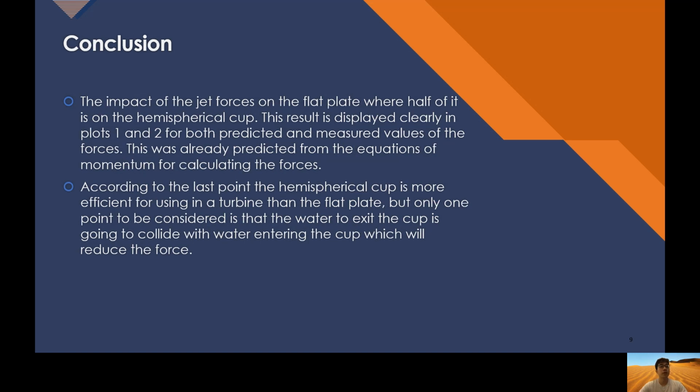So in conclusion, the impact of the jet force on the flat plate is about half of that on the hemispherical cup. This result is displayed clearly in plots 1 and 2 for both predicted and measured values of the forces. This was already predicted from the momentum equation for calculating the forces. According to the last point, the hemispherical cup is more efficient than the flat plate when used in a turbine. But one point to be considered is that the water exiting the cup is going to collide with water entering the cup, which will reduce the force.